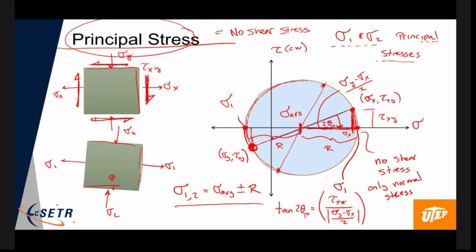Okay, so you can easily figure out not only what the principal stresses are from Mohr circle, you can also figure out what's the orientation. We can get this angle theta that puts you into the principal state. That's a little harder to do from those 3 equations, 9, 1, 2, and 3, okay? So that's the principal stress. Really important. Most material failure theories are in fact written in terms of the principal stresses, okay?